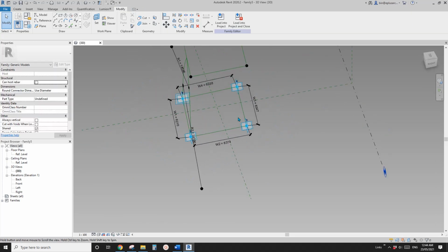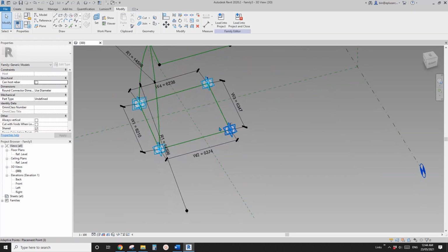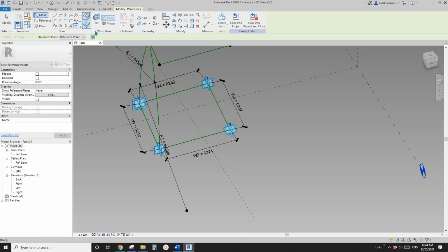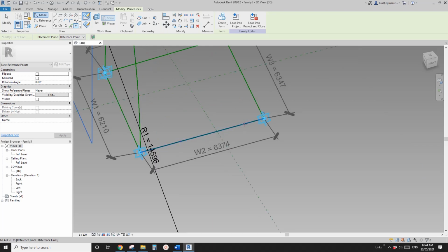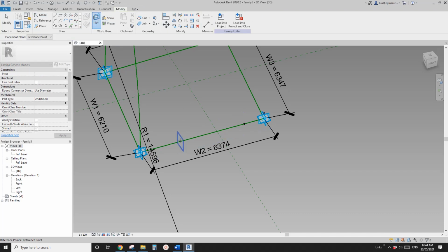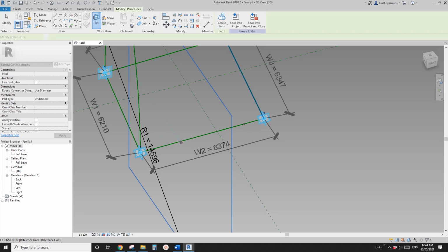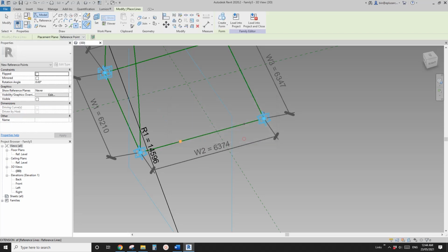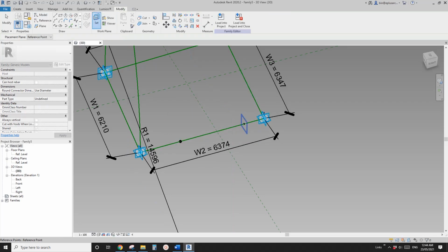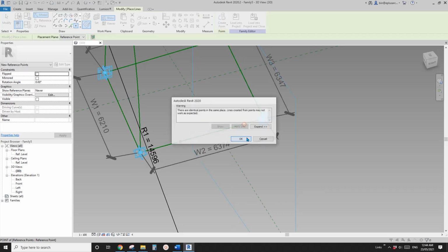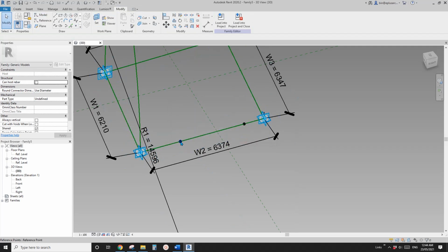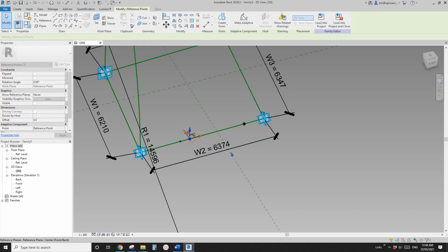And then we need R2. So we just do the same, point, draw on face, point 1, let's just place another one here, and then point, draw on work plane, set work plane, pick this work plane and place it on the point. Okay, so another one, and place it on the point. Okay, so select this point, go that way, that's okay.